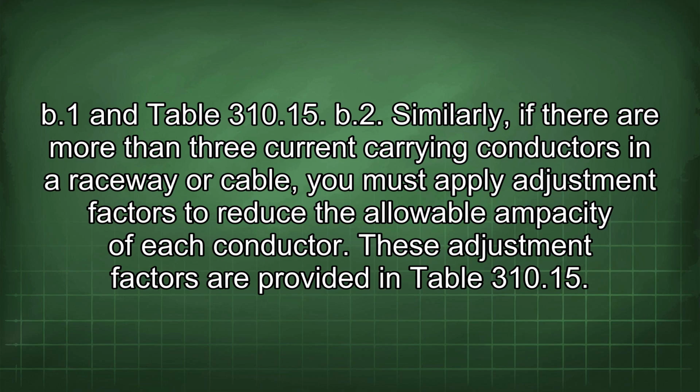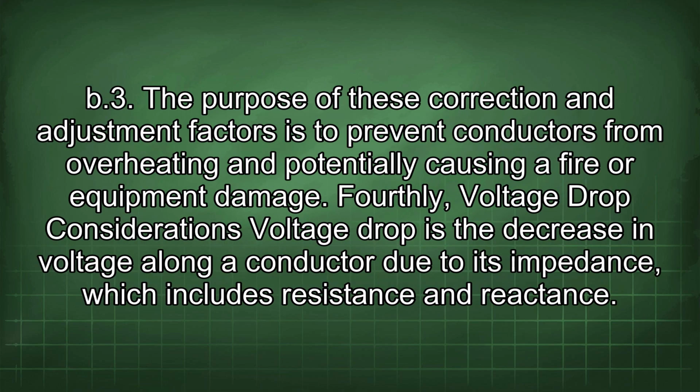These adjustment factors are provided in Table 310.15.B3. The purpose of these correction and adjustment factors is to prevent conductors from overheating and potentially causing a fire or equipment damage. Fourthly, voltage drop considerations.